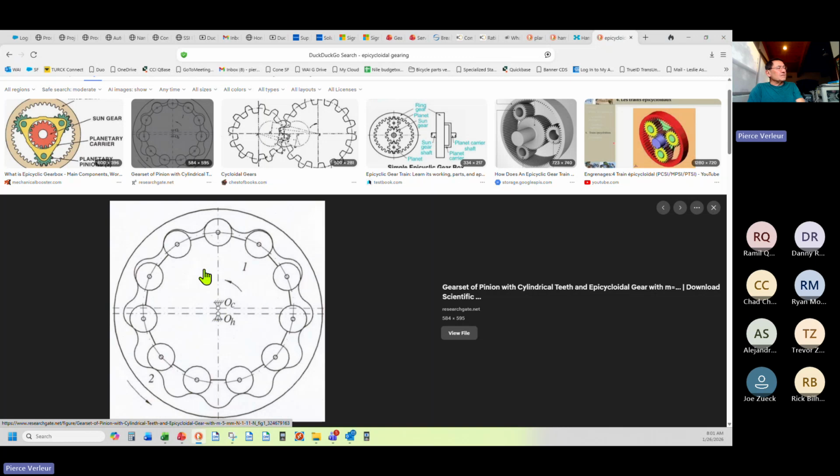One of the other advantages of this versus harmonic gearing is this is super stiff. Look at all the contact that you have. There's no flexing elements here. You've got lobes on bearings here. So it's extremely stiff. This is an ideal gearbox for that antenna application I talked about earlier.